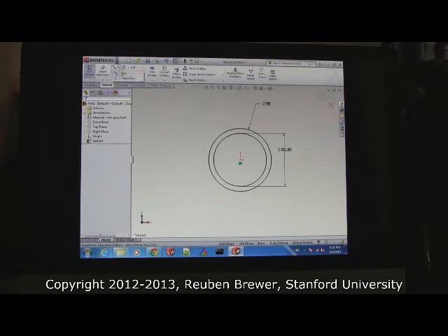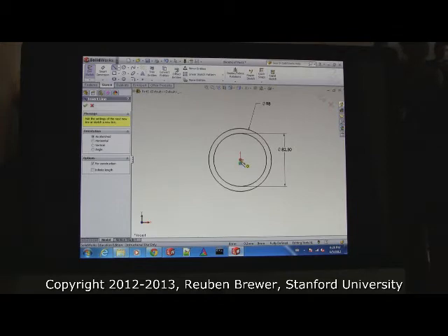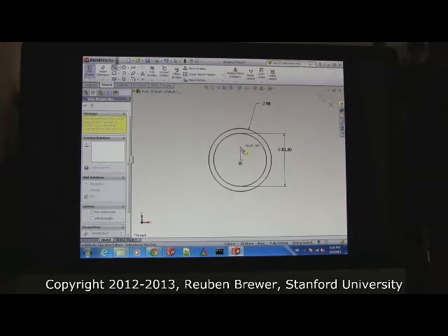Okay, everybody take a dashed line, put one line in the middle, and I want to show you something. So if your cursor is directly above the center point, you see how it kind of snaps there to make a vertical line, and a yellow thing appears that shows a straight up and down line? That's SolidWorks trying to be smart, saying, hey, you're making a vertical line. It's like the talking paperclip from Microsoft Word back in the day that tried to assist people in writing annoying letters. And now go down, and you see how it snaps to a horizontal line? So we can use that to our advantage.